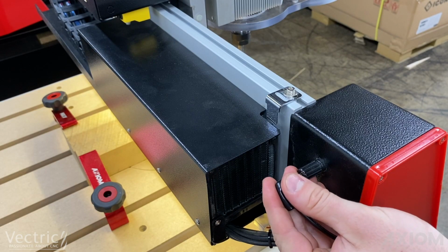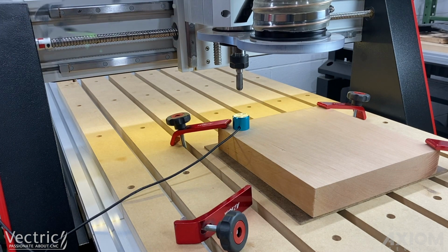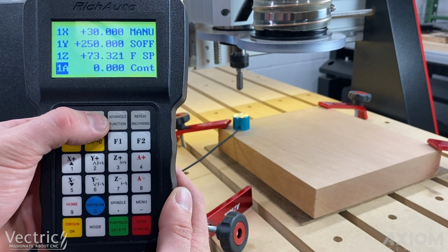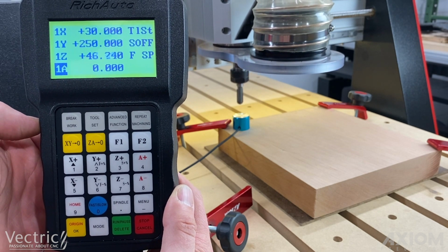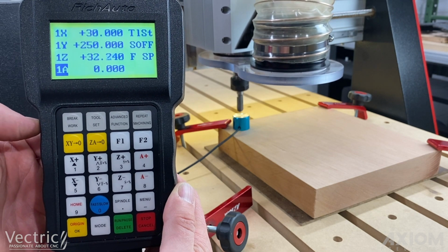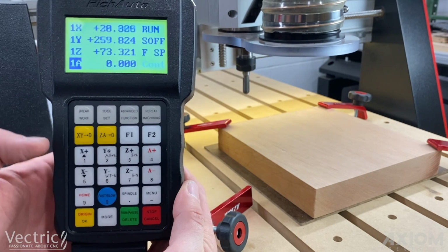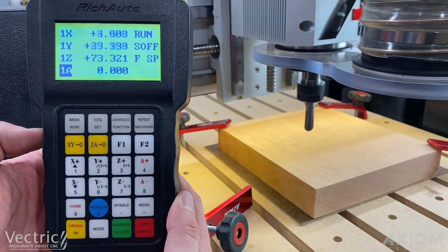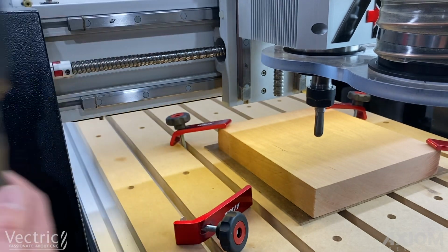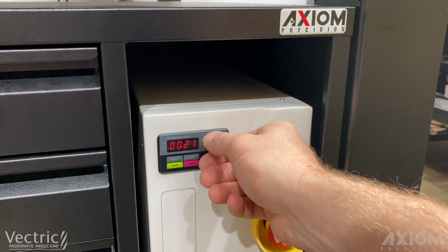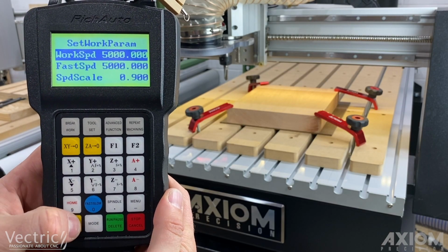Plugging in our touch-off puck, we're going to go ahead and touch off on top of the material. We're going to use this same position throughout the entire piece. Hitting the tool set button allows that to come down. At any time in the project, you can hit the OK button on the control. That's going to return us back to that origin point so we can just visually reference it. We can see that it's set at 0, 0. So at this point, we're good to go. After setting the RPMs, we'll select our file. And we're off and running.